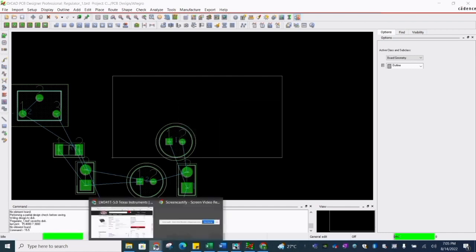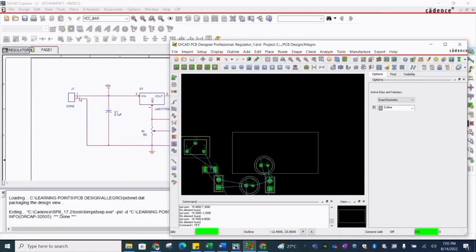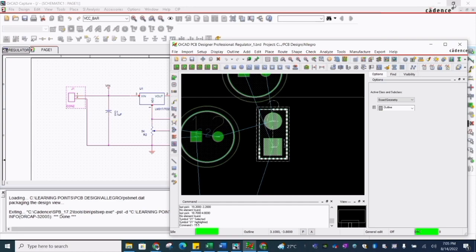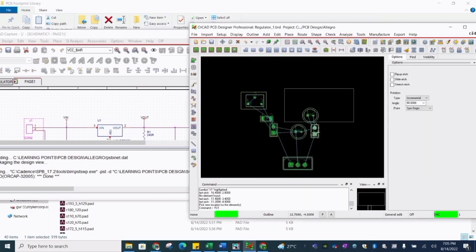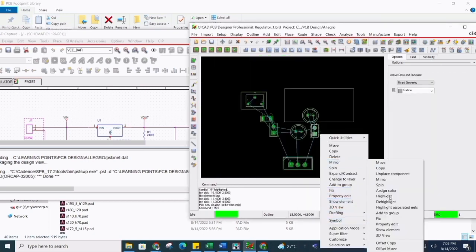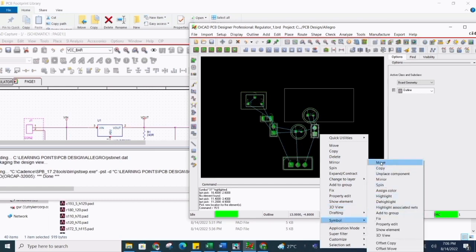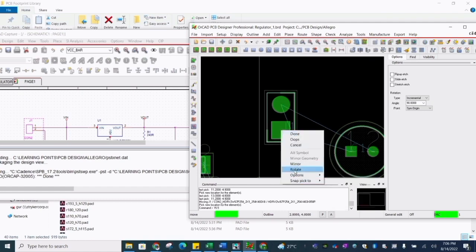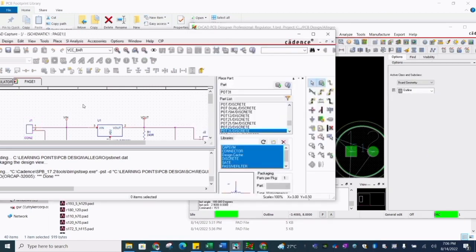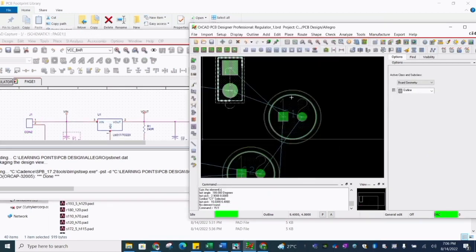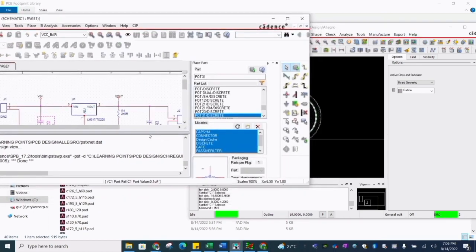If you have two screens, it is better, since one screen you can utilize for schematic and another for PCB layout. In case you have a big screen, you can half utilize for schematic and half for layout. So that's how you can easily place the components and see both schematic and layout. For me it is quite difficult since I'm using a small screen. Yeah, this is how. Just place as per circuit flow.